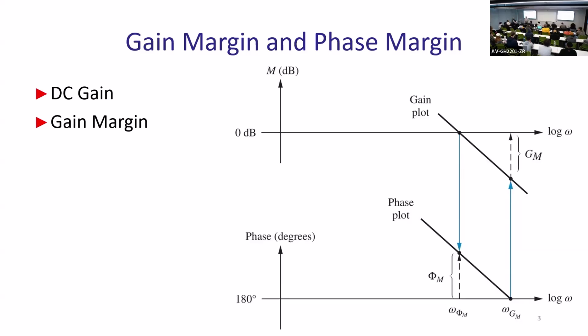Same thing with phase margin. So phase margin is where your plot here is crossing 0 dB, which means gain of, what is real gain? What is 0 dB? What is the gain of the system? Not gain 0 dB. So by what are you multiplying the input? What is 0 dB in regular units? It's 1. It's gain of 1. Because log of 1 is 0, 20 times 0 is 0, 0 dB. So you have a system with gain 1, which means all the input gets to your output.